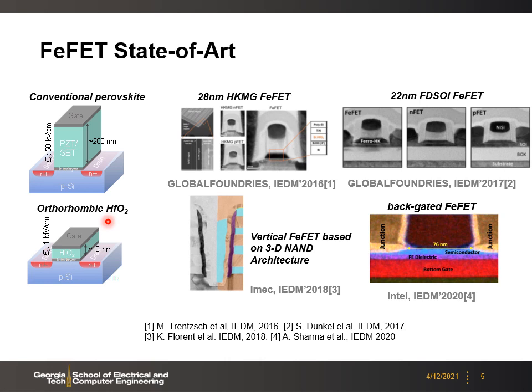So here we review the state-of-the-art research and development results from industry in the past few years. For example, GlobalFoundries demonstrated a 28 nanometer high-k metal gate bulk FeFET at IEDM 2016, and then a follow-up work on the 22 nanometer FDSOI FeFET at IEDM 17.